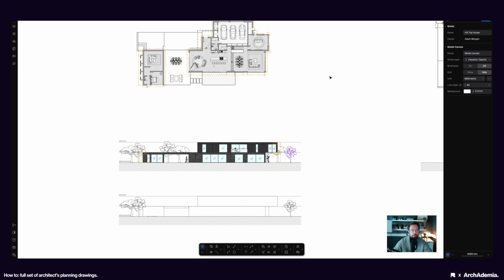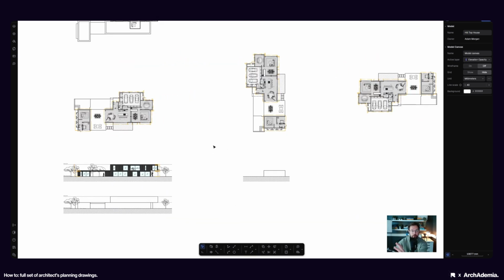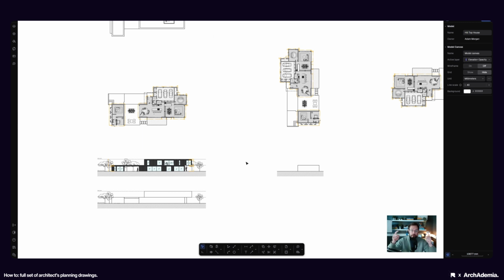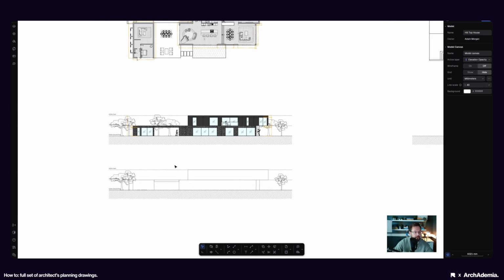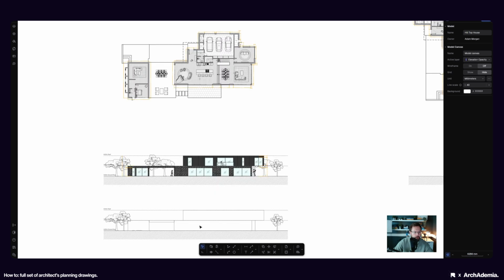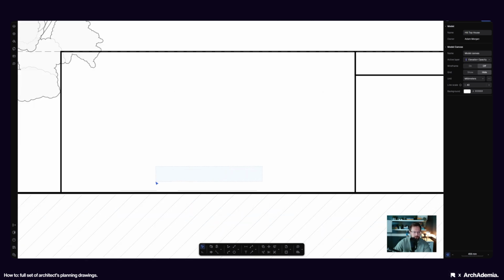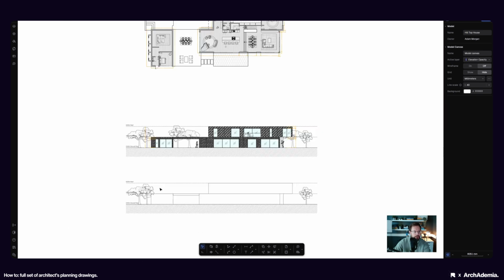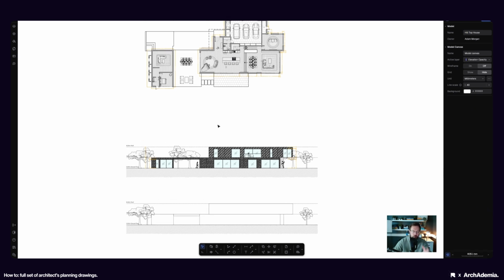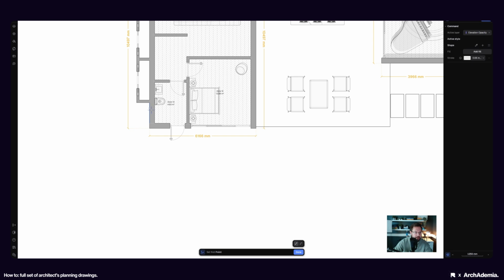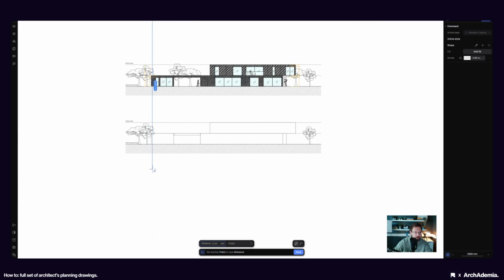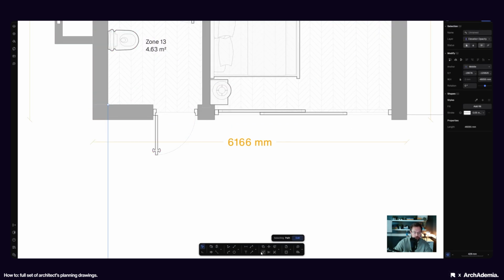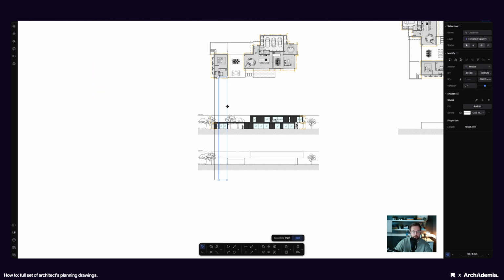So I would encourage you to work up all the other elevations, and then at least then you've got the bones of a section. Now, the problem with sections is sometimes it's hard to picture what the thing is going to look like in section. There's more to it than just the striking of lines down. Now, just to demonstrate something, we can, of course, strike the lines down, and what we want to do is include the wall thicknesses, like so, okay?